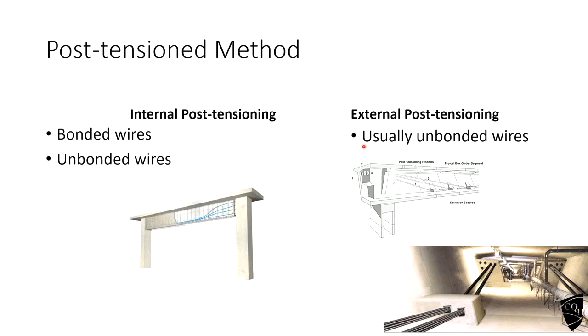So these are very similar to RC beams. In RC beam also we have depth. In RC we put the location of the bars. Here also you need to tell me where to apply the compressive force, the location of the pre-stress force. The next one, you should be able to tell me the amount of AST, how many bars I should provide. Here, the amount of pre-stress. So very similar things.